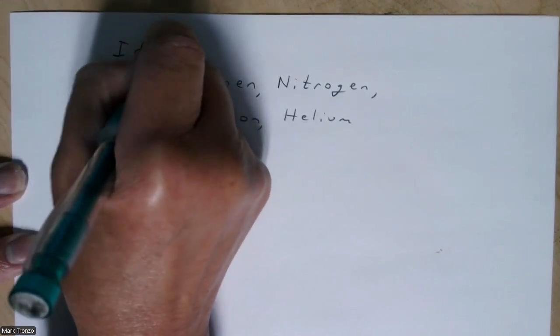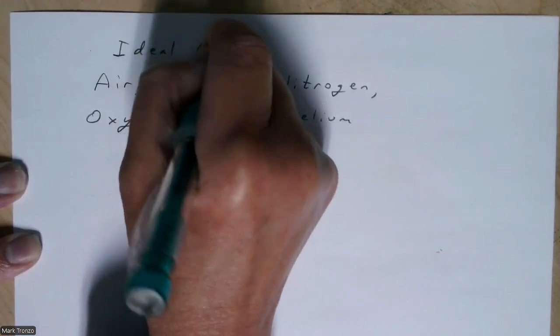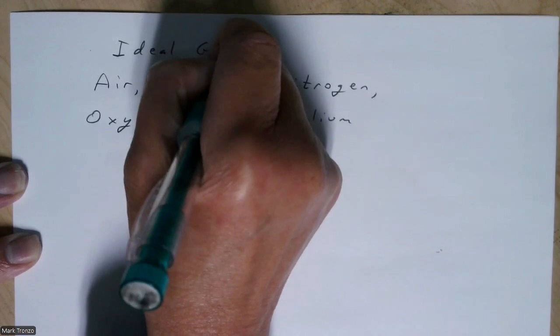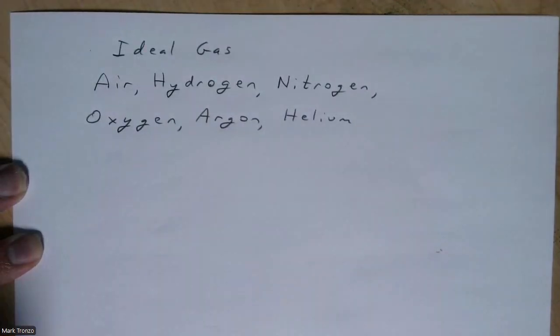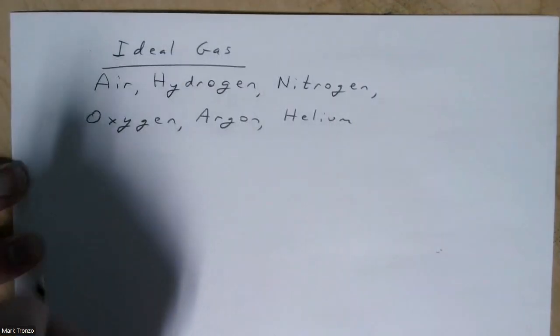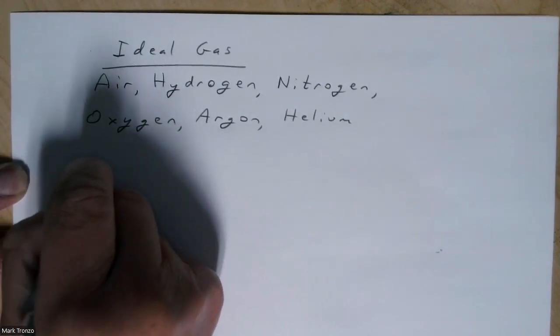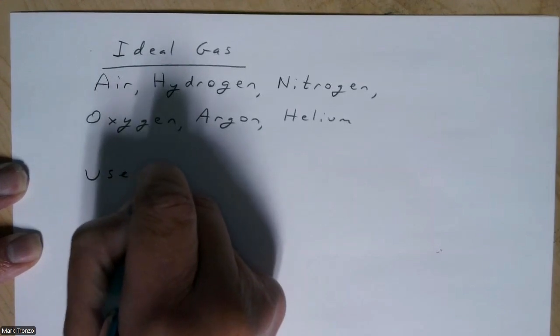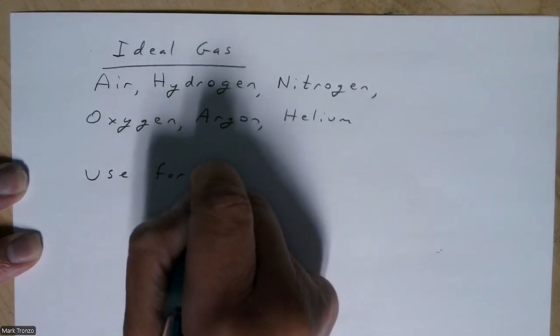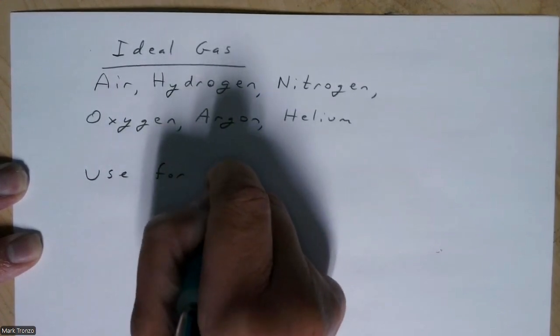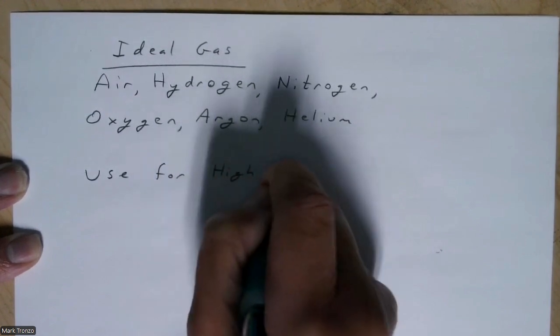So these are good applications for the ideal gas law, or the ideal gas equation of state. In general, use it for high temperature, low pressure applications.